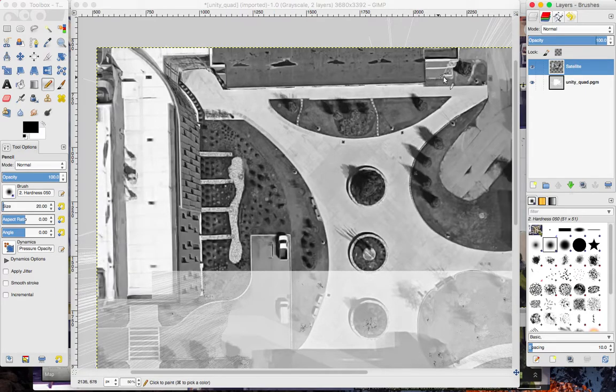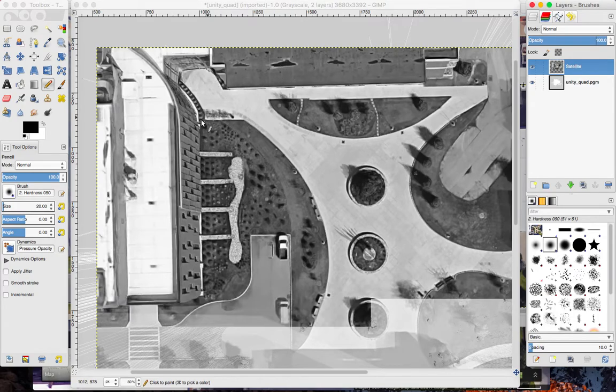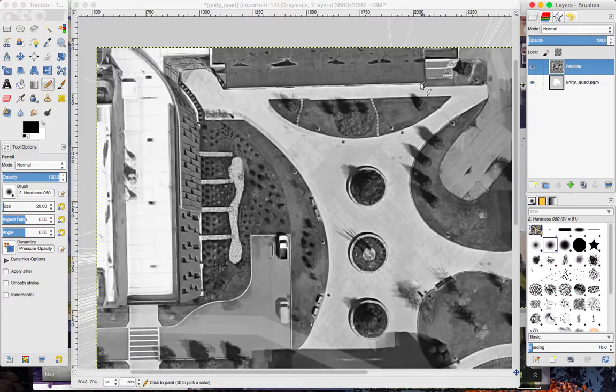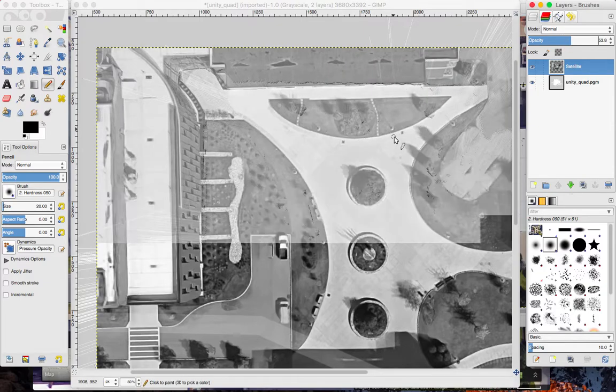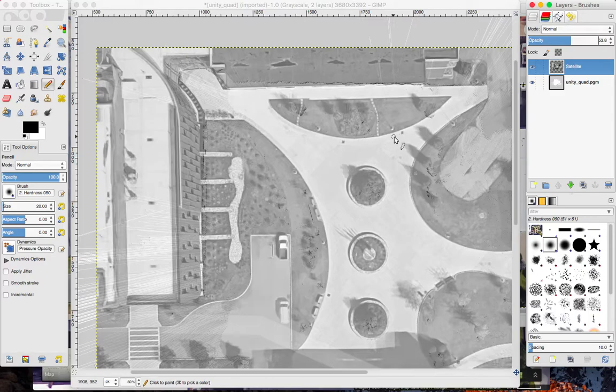So you want to look at this part right here, and this part, and then make sure you look at the other buildings' ground portions, not the overhang, because the overhang is not what the LiDAR map will see. Remember, the LiDAR, at least the last time we set it, was at about 2.5 meters and higher is what it's seeing. So just keep skewing this until you get it right.